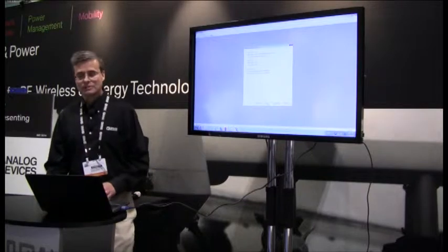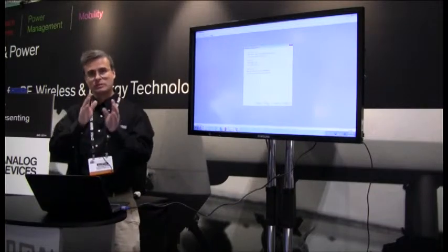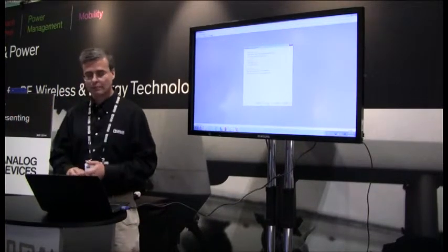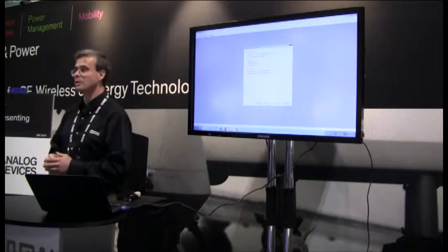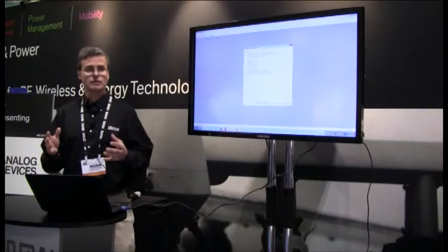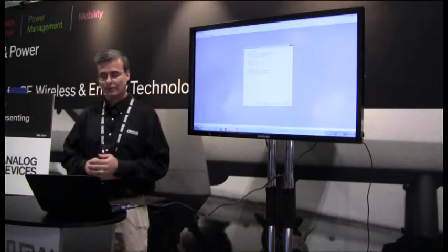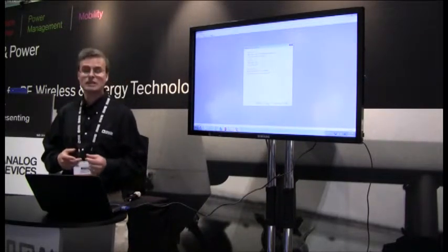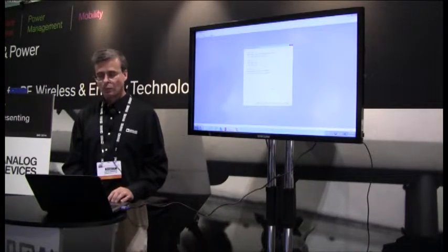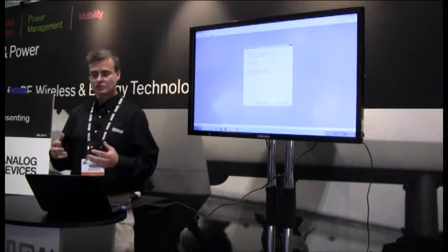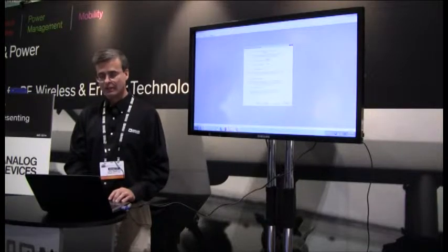The next thing it gives you is the choice to be able to either produce a range of frequencies, because a lot of times you use it to be able to get to different frequency points and you want to be able to sweep between different frequencies, or sometimes you just want one single output. And your loop filter is going to be different for those, and your different parameters, everything's going to be different based on those. So you have the choice to be able to do that. You also have the ability to choose either integer-N or fractional-N PLL as well. And you can also have it make sure that it actually gets you on exactly the frequencies that you would like to generate.